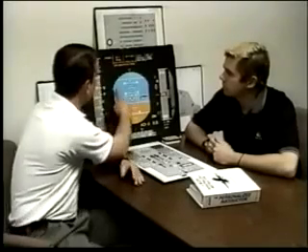Finally, there's another law called abnormal attitude law. If you have these protections available for bank and pitch and so forth, how would you ever enter this abnormal attitude law? Well, you definitely can't get there yourself. You have to be put there from some outside source, such as a wingtip vortice or wind shear, some kind of outside force causing the airplane to roll or pitch up.